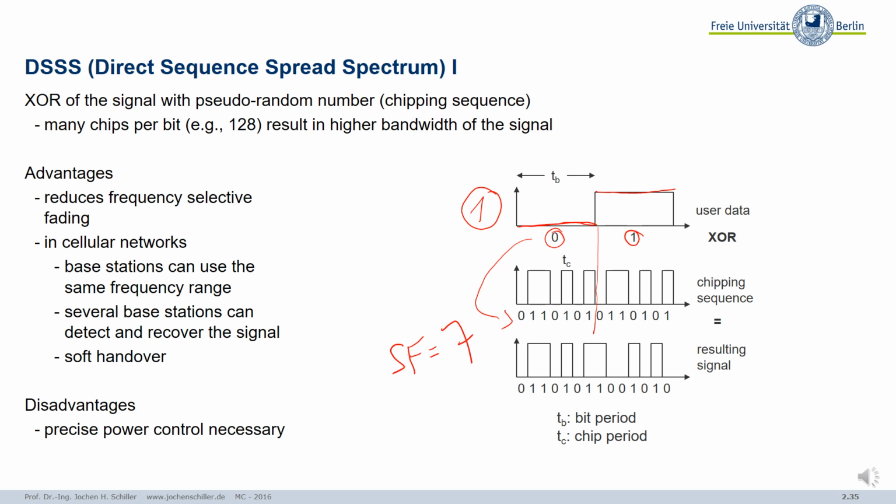And if we now use the same digital modulation scheme we can use for the original data, we expand the spectrum we need by a factor of 7. Because we have 7 times more potential changes in our chips, and then depending on how we code it, frequency or amplitude or phase shift.